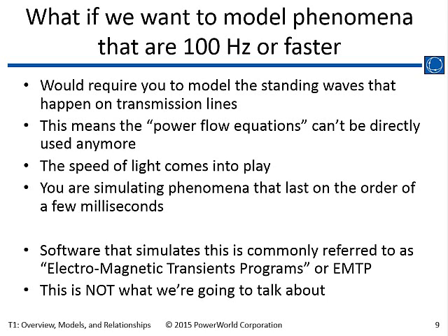So when we do transient stability studies, we're going to use a time step of about 4 milliseconds. In 4 milliseconds, light can only go 700 miles. So it cannot cross WECC in one time step. But in doing our modeling, we're going to assume that it does. So there's a bit of a trade-off in the modeling here.